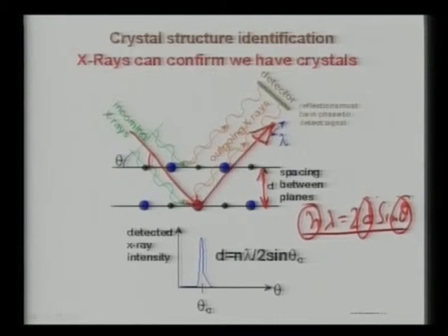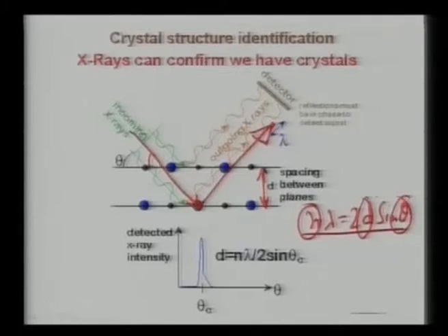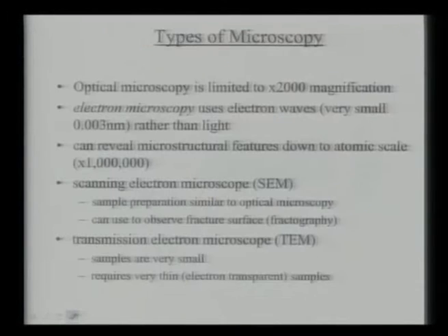Now, depending on the material and its composition, every material will diffract the X-rays at a characteristic wavelength and at a characteristic angle theta. Once we have the plot of intensity versus 2 theta, you can find out that whether it is copper, nickel or iron, it will have a characteristic peak, and that is the way you can find out the presence of different materials or different phases in a microstructure.